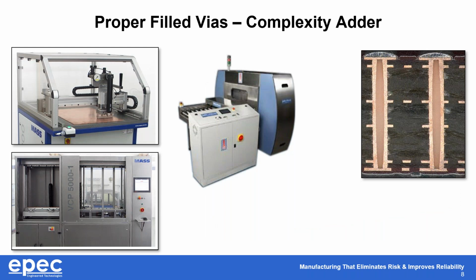One of the other things that most companies don't recognize that add a substantial amount of time are filling vias. And the whole thought process is, the picture on the right there is where most customers would like to see how they want to see the vias filled. They want to see them filled completely, no voids, no air bubbles, and then plated over the top. And it's very, very easy to do that if it's done properly.